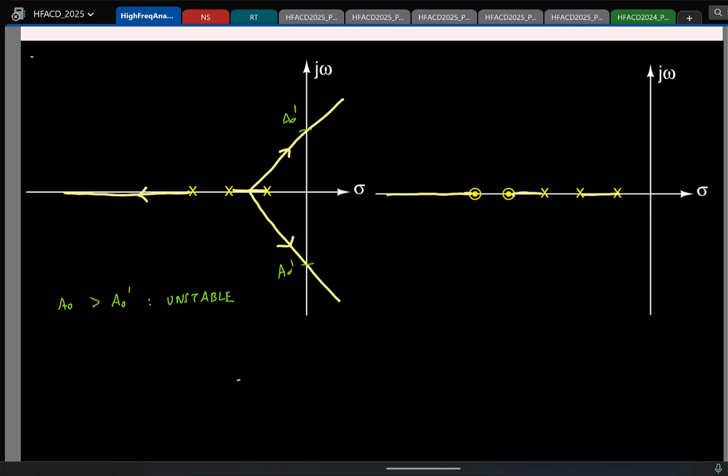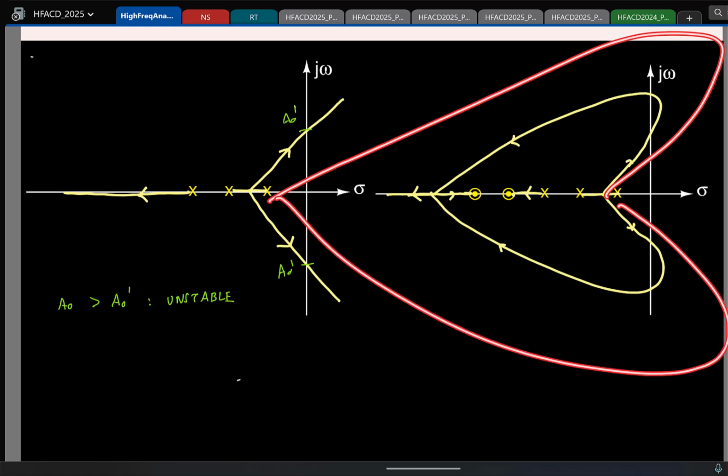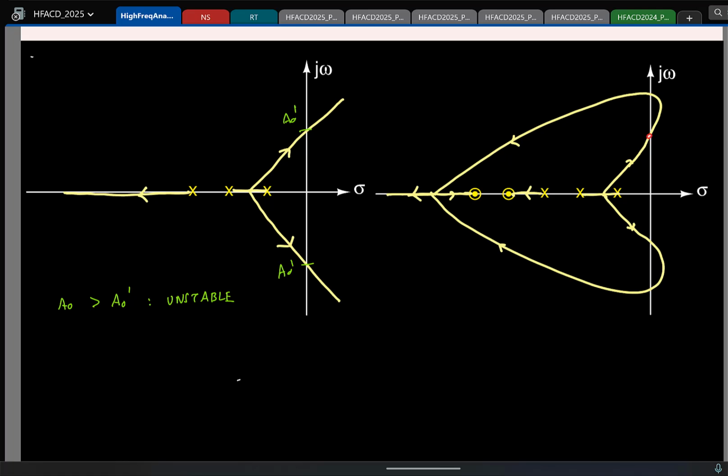Again, the way to visualize this is as follows. Let us say there are no zeros. Then we know for a fact that the poles would have done something like this, right? But now the zeros are present, which means they cannot do this forever. One of them has to terminate here, and that is already happening here, correct? One of them has to end here, other should go to infinity, right? So the logical thing is it might do this. Now again, depending on how far or how close the poles and zeros are, this might not even enter the right half plane. It might just do this also if the zeros are close by. If the zeros are far apart, it might be in the RHP for a longer time and then it will do this. But for now, we'll take a case where it enters the RHP for small values of gain.